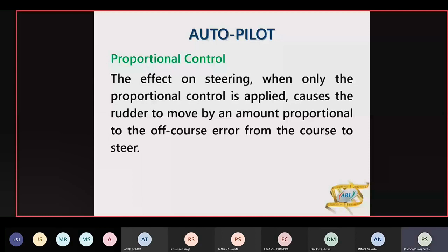Similarly, when we come to 317.5 degrees, rudder 2.5 degrees. Do you think the vessel will be controlled and steady at 320, bringing the rudder to midship only when the difference is 0? Can the vessel stabilize on 320?